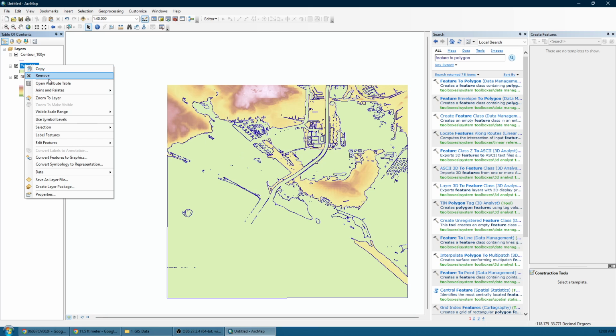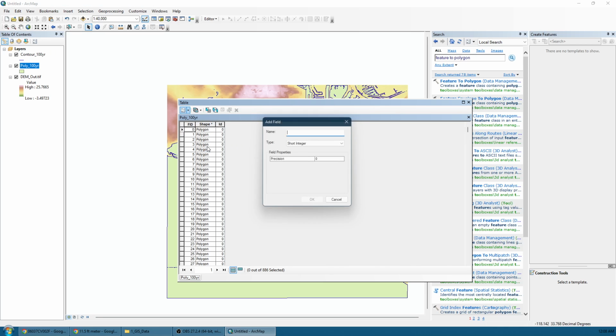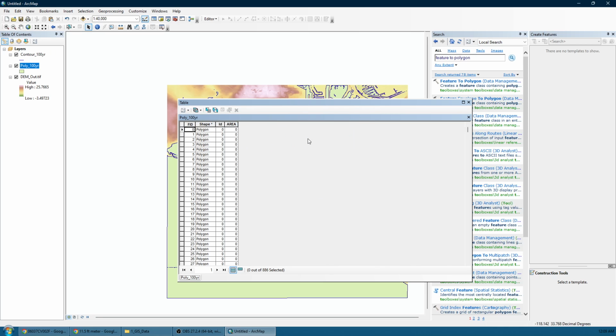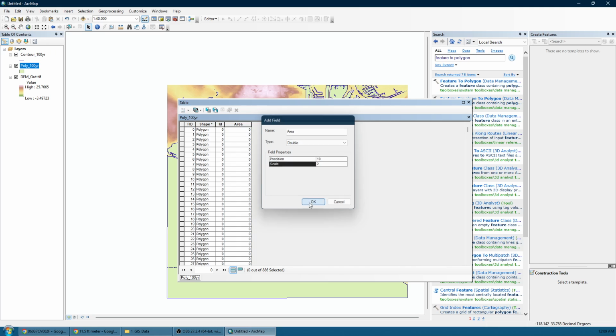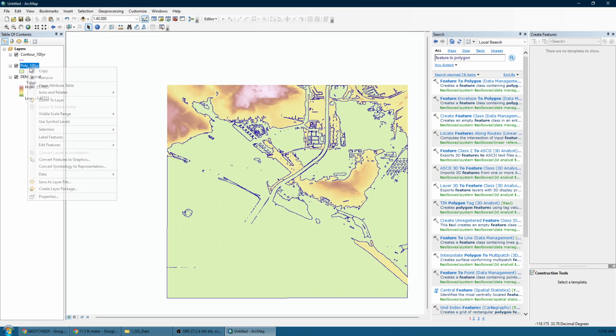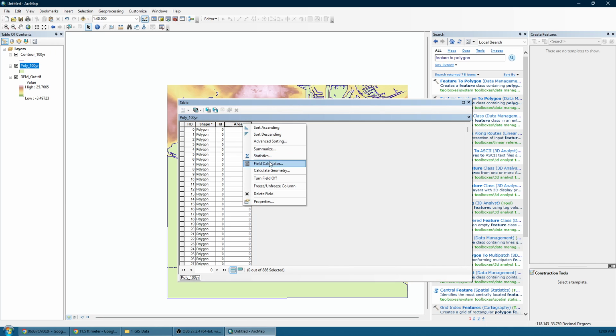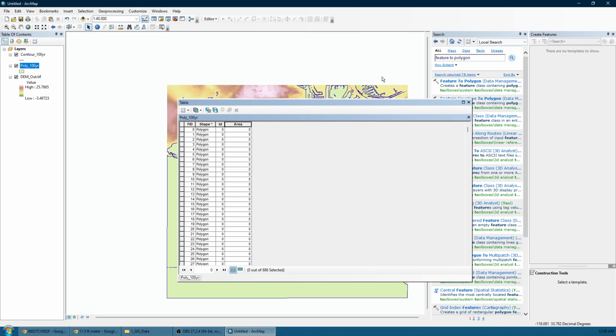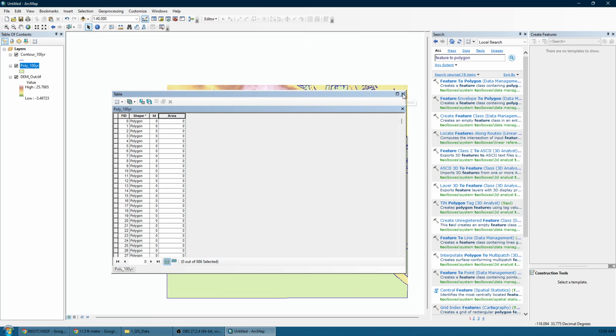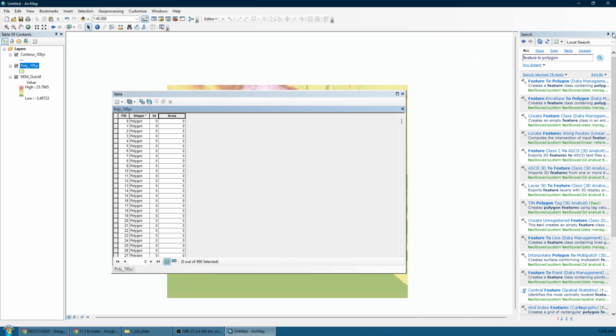It gives you a lot of polygons here. If you look at here, add field. I think the projection didn't work here, so just change this to 2. So you cannot calculate the area. It's because you have to change the projections. Right now we're at latitude and longitude, and you cannot do it here, so you just need to project it.